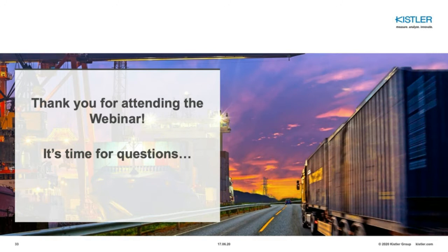And I think we all agree it's very important that the sensor adheres well to the ground and the grout to the pavement, so as not to have any safety risk on the road. I think that would really be the worst case. So that's the big reason why we need to stick to these rules and make sure that there's no humidity and a high enough temperature during the installation.